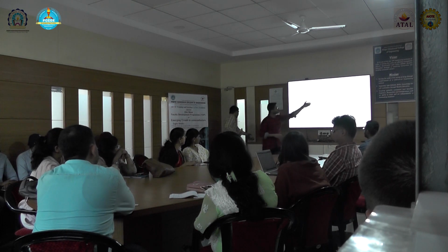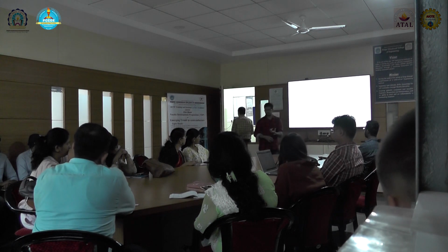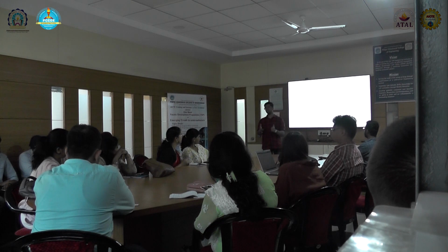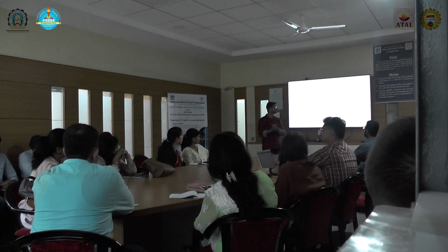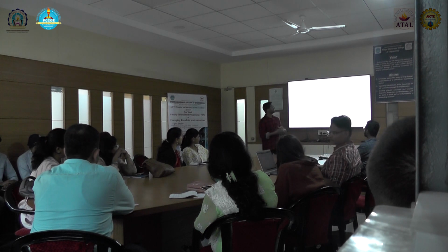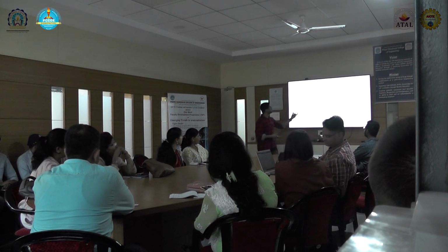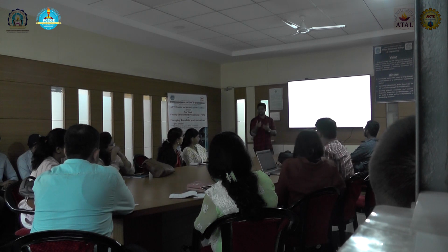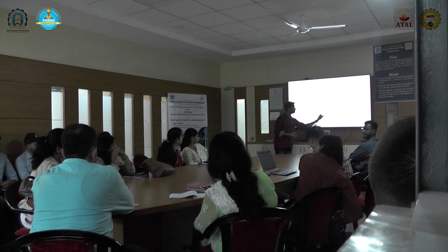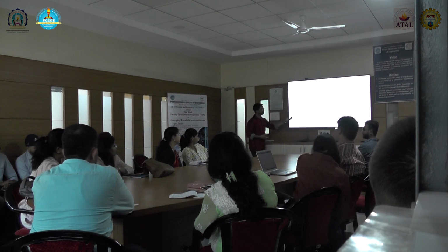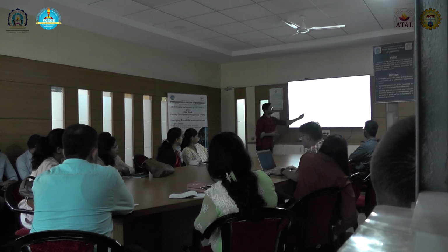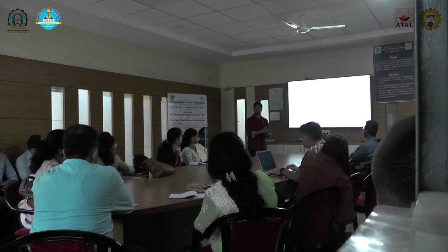Request indicates a new request and it's a pulse signal. It can be asserted when the interface is not busy. We all know that if the interface is busy, we can't send a new request. Then we have done. Done is used to indicate that our request is completed, and it can only be asserted when an interface is busy. Meaning we got a request, the interface is busy, and now it's waiting for done. Then busy is used to indicate whether the interface is busy or not busy. So busy should be asserted after the request is sent, and it will get deasserted after we get the done.